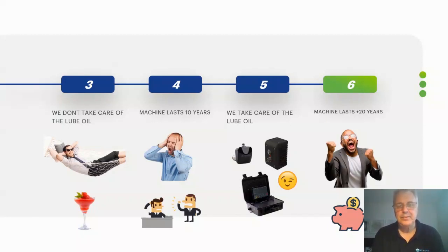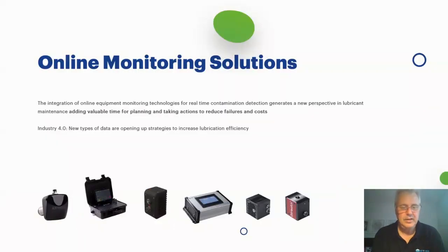But okay, this reminds me, thinking about something else, that along the asset's lifetime, it's possible that modifications are made to the machinery to increase speeds, productivity, and so on. In this case, please check if any changes need to be made in the lubrication program in order to assure that the performance in the lifetime of the machinery will be respected. It's very important to redo the calculations if necessary. Okay, just have a note aside.